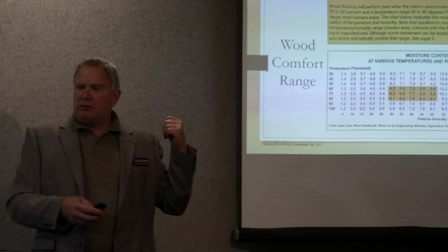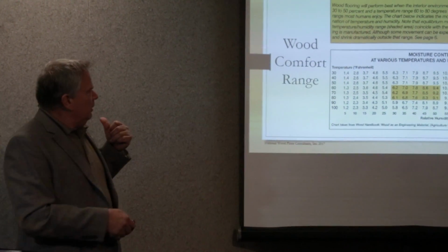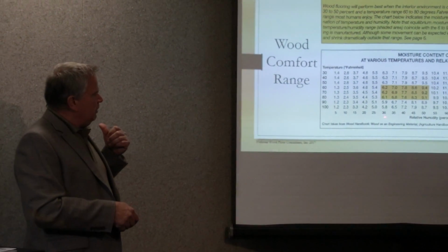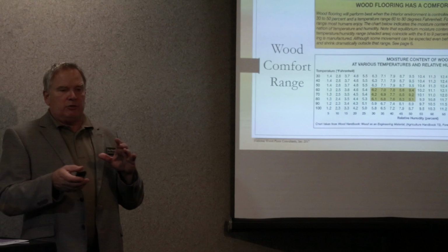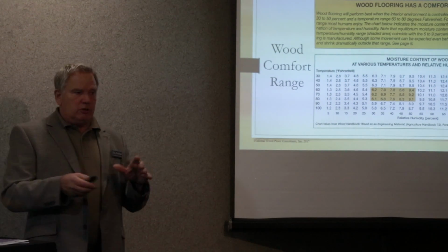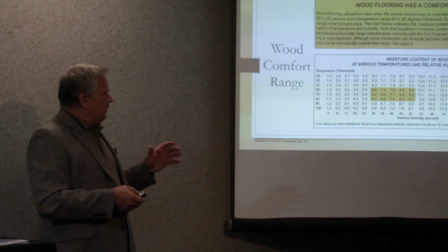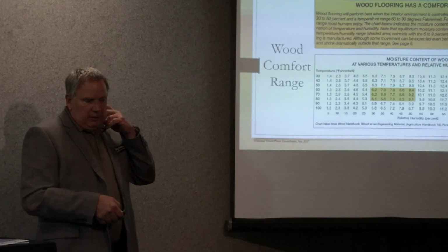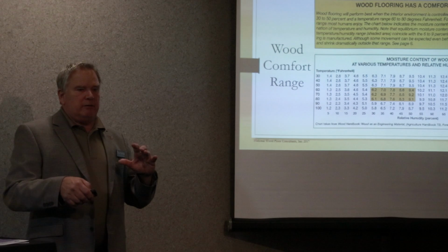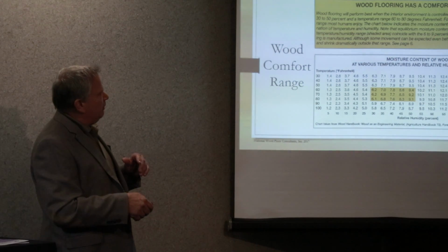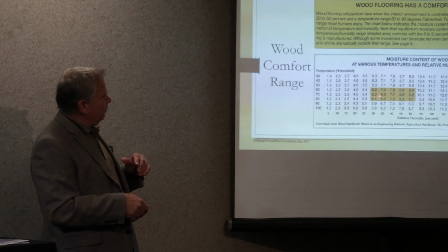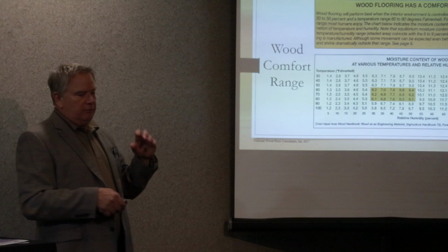When the wood is cycling from winter to summer, and we talked about that 128 inches with that 3/8 growth in it, in the winter that comes back to our 6% moisture content, and that would be your 30% relative humidity, it's going to show those gaps of 3/8 of an inch. It's going to show up somewhere. That's why it's really critical to see where they were well over their 9% mark on their wood. But when this comes back, the wood will travel at whatever the level, the temperature and relative humidity, it will bring an equilibrium of that moisture content.